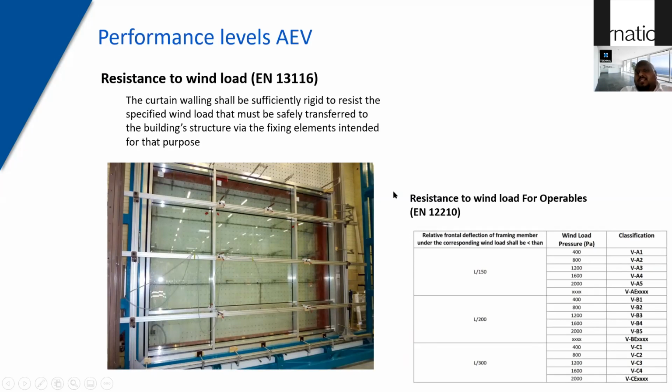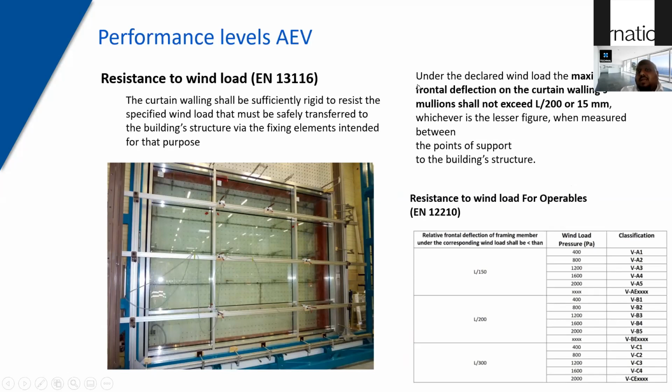Resistance to wind load is defined by wind tunnel studies and desktop analysis, which give you a clear idea of what wind pressure the building needs to be designed for. Over design could complicate the facade and make it more expensive, and under design poses a risk. So it's very important that you work on a sensible approach to ensure that there is no risk involved.